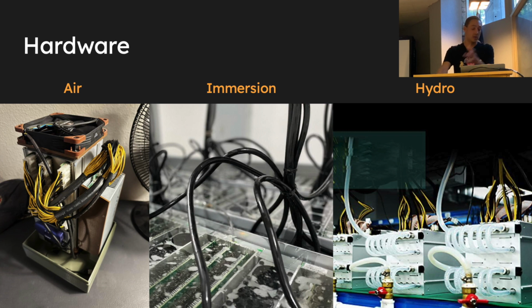So these machines are silent, essentially. They run pumps, and you can overclock typically higher than air-cooled machines. And the benefit of that large amount of insulating fluid is it helps prevent against thermal shocks from expanding and cooling, heating up and cooling the control boards, the hash boards, when you cycle the machines. That can damage your hardware over time. You don't want to cycle it too often. You want to ramp it down, not just kill power. So that kind of solves that problem. Immersion machines are highly resilient in that regard.